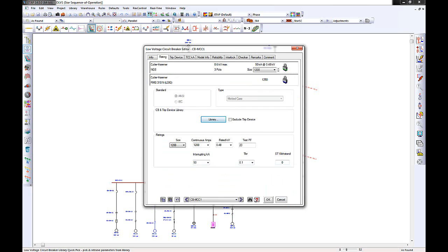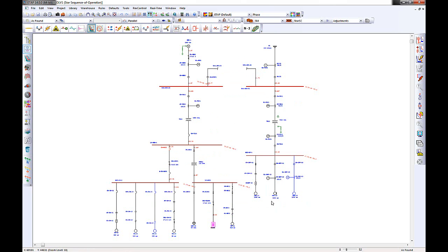So as far as you have linked your models to the proper library model, then the rest is not that important. The program would evaluate your setting and give you the problematic areas for protection and coordination. Naturally, the best starting point is to have the as found setting or applied setting if you have an existing project to start with.